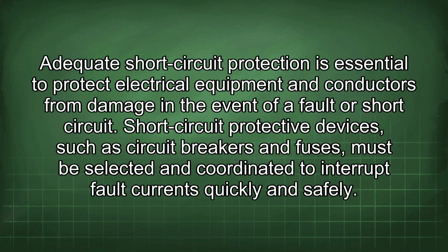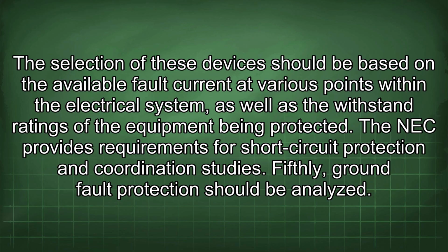Fourthly, think about short-circuit protection. Adequate short-circuit protection is essential to protect electrical equipment and conductors from damage in the event of a fault or short circuit. Short-circuit protective devices, such as circuit breakers and fuses, must be selected and coordinated to interrupt fault currents quickly and safely. The selection of these devices should be based on the available fault current at various points within the electrical system, as well as the withstand ratings of the equipment being protected. The NEC provides requirements for short-circuit protection and coordination studies.